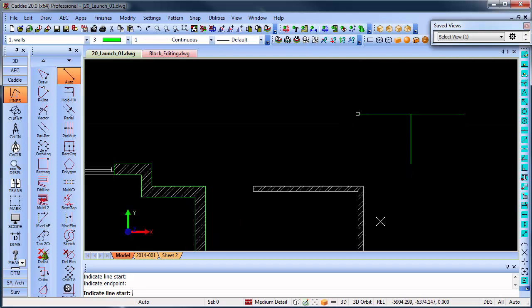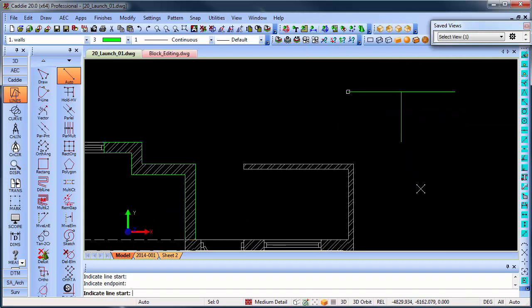So basically the equal sign now allows you to project, using your polar snaps, any given points to a point. The equal sign then will move your cursor to that particular point, which means any command that you're busy with, you can now do from that specific point and continue in any direction that you want to.